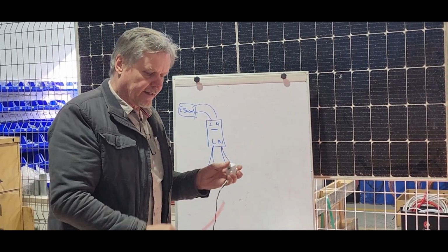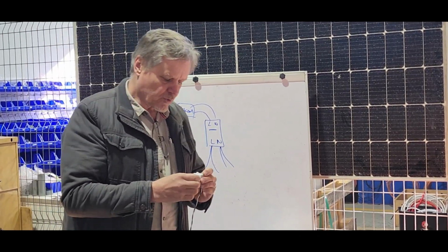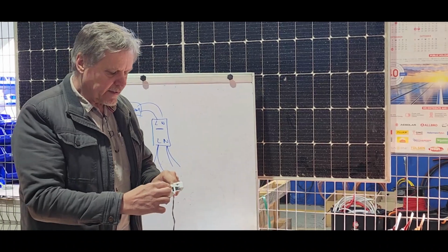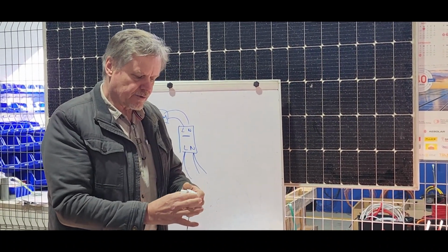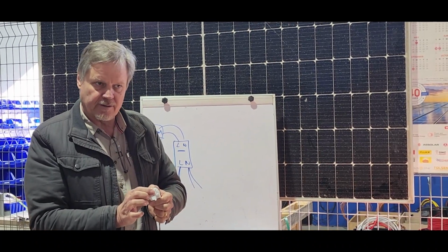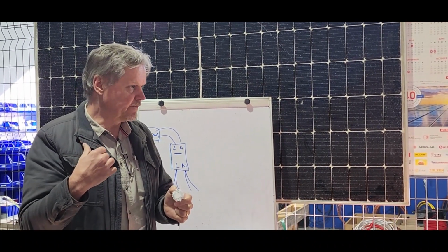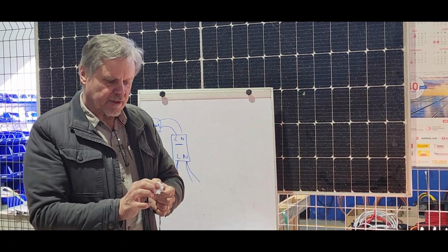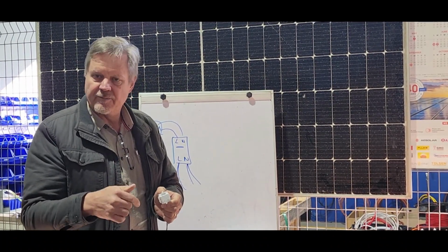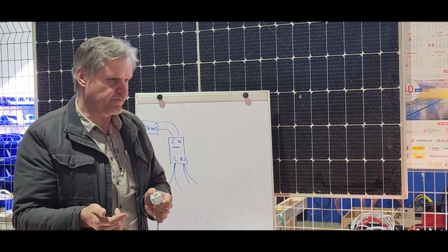Okay. And this CT, these are split core CTs. Most CTs are actually solid CTs. The core inside needs to touch, it needs to be properly closed. So when you put the CT on, yesterday I had to go fix one site, the CT wasn't closed. The data we got from the monitor didn't work. So you need to hear that click, so that you know the CT is closed. Otherwise, we're not getting usable information from the CT.